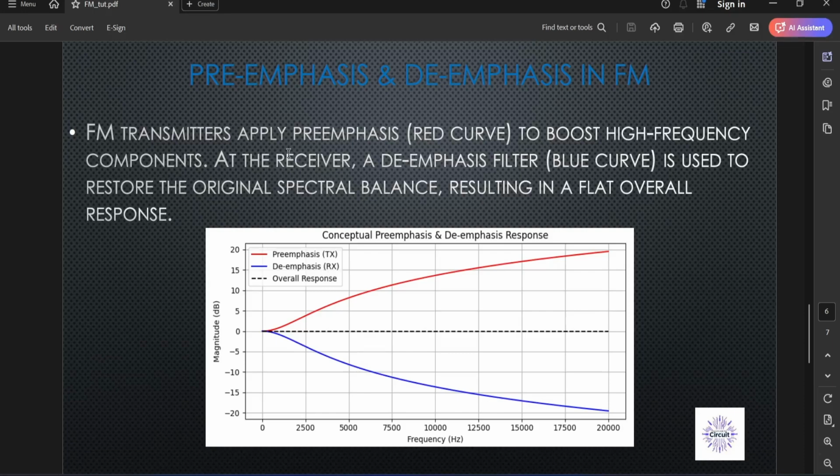As you know, one thing is that when the transmitter wants to transmit the data, higher frequency information might be weaker compared to lower frequency information. And that means that they might be more prone to noise. So when the noise is added to that part of the spectrum, it may cause more SNR degradation because S, which is the signal power, is lower in that region.